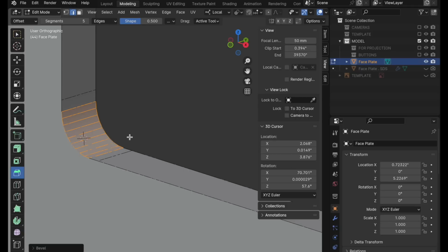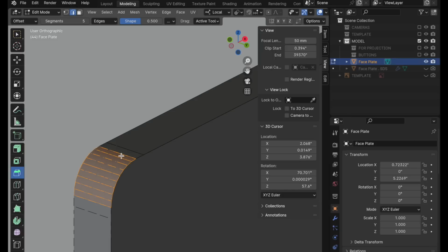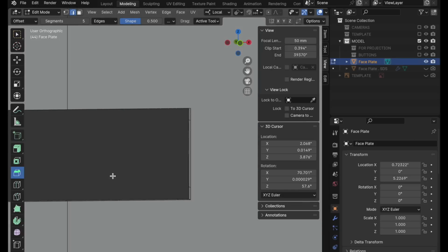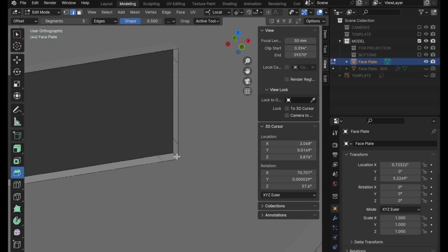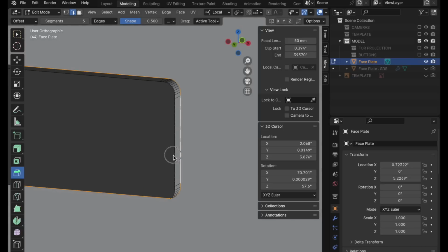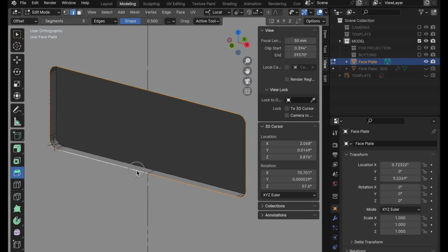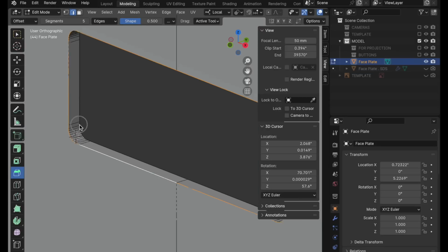But we have the boundary here and the boundary here to prevent shading from going into the flat regions. So there we go. And then we just come up, Shift R, and replicate that around to the other side here and here, Shift R. This design detail has a bit of a large bevel. So let's double click. We'll get one half of it. Hold the Shift key, double click to get the other half.